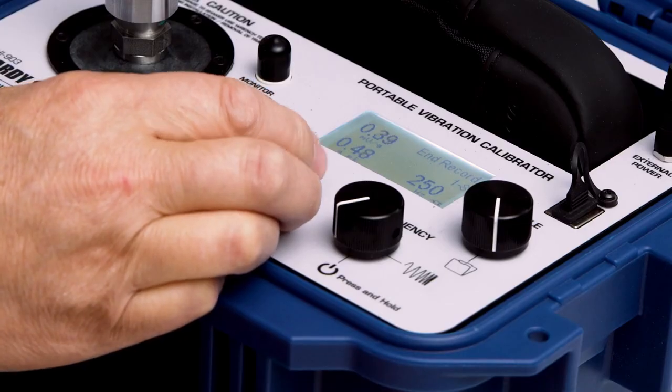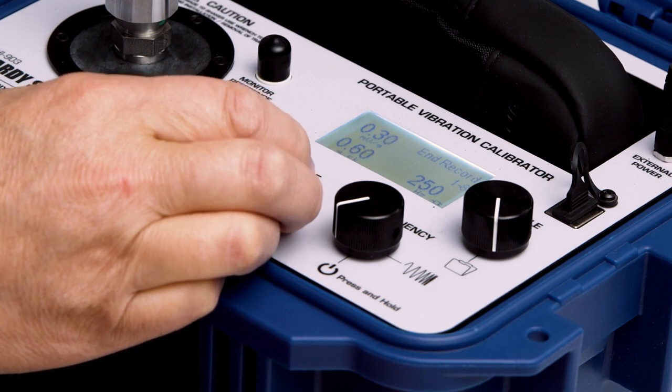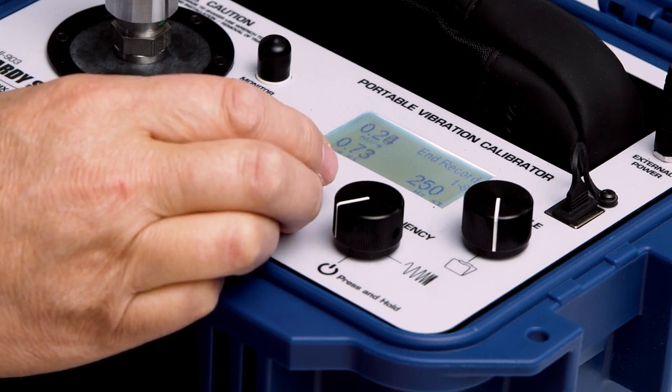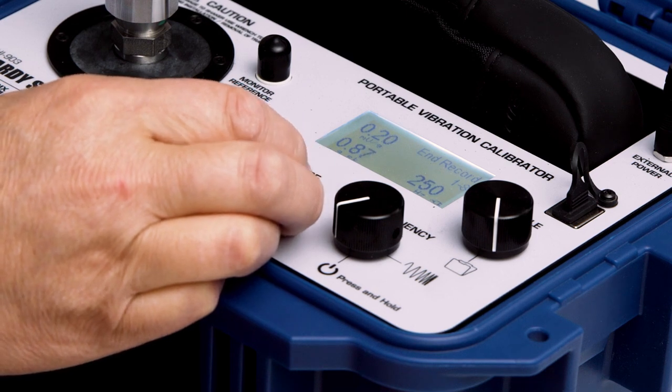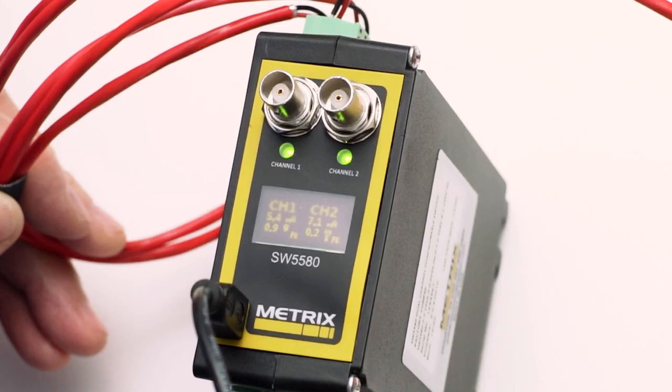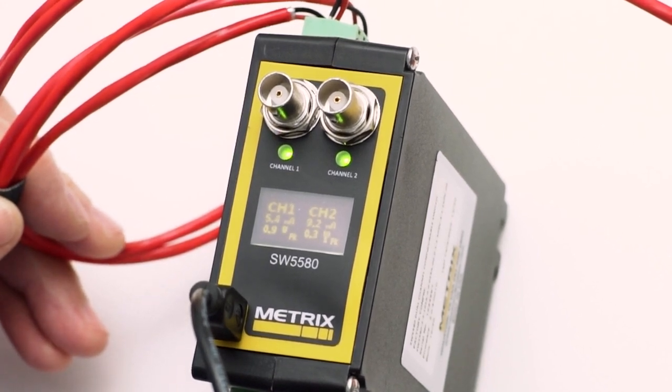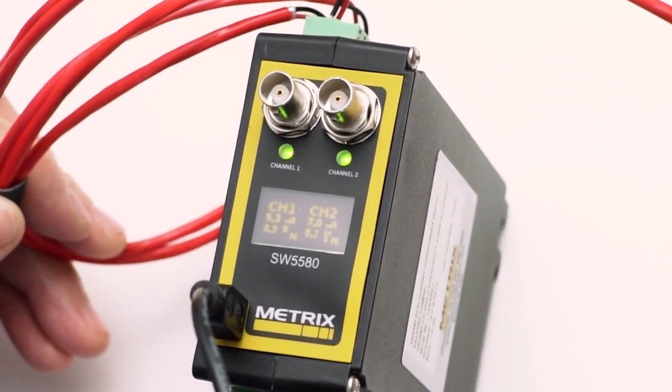So we were at 0. I'm going to go ahead and increase this to 1G. And our alarm was set at 1G, so we'll go to 0.9 Gs and there shouldn't be an alarm. Okay, 0.91. And there's no alarm, it's still green. Let's go to 1.1 Gs and let's see the alarm come in.